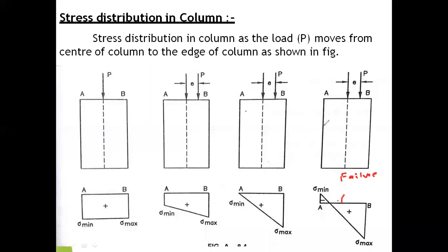Here the reversal of stresses happens. Look, reversal of stresses means negative stress and positive stress. Here only positive, here only positive, here only positive. That means the possibilities which are acceptable in real applications are only these three. The rest are not at all acceptable. Why? Because the reversal of stresses will damage your structure more.